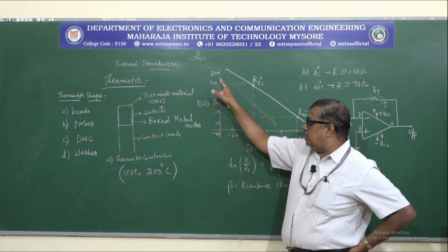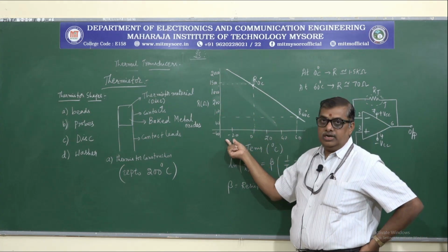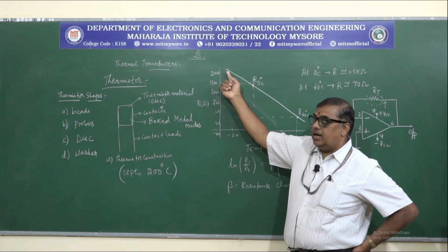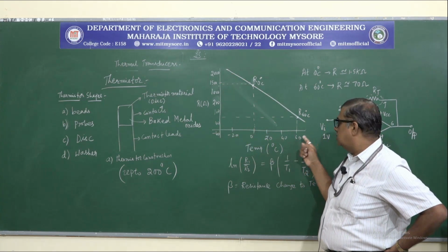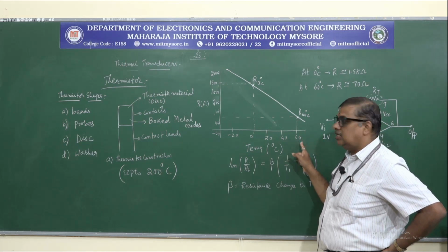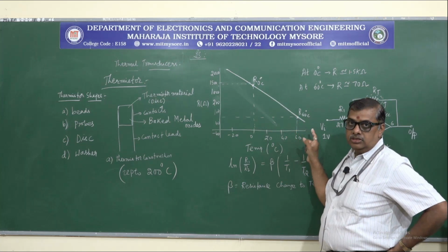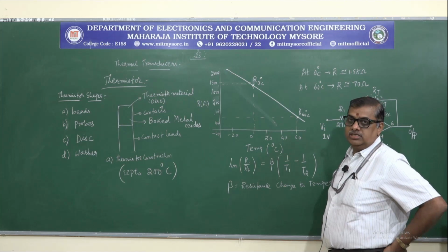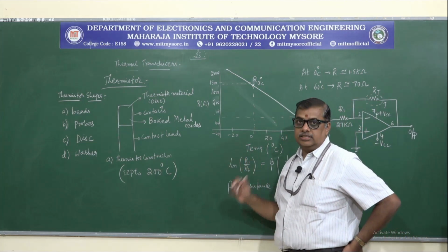This is a typical graph of a thermistor where at the small temperature, here minus 20 degrees, in the negative temperature the resistance is very high. As the temperature increases in the forward direction, the maximum I have taken here is 60 degrees. For 60 degrees the resistance has come down. This is called negative temperature coefficient. All thermistors are negative temperature coefficient materials.